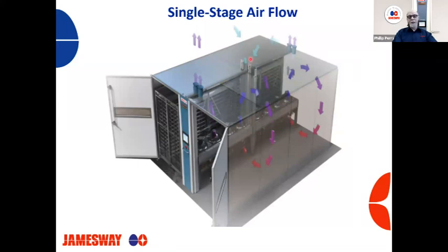But anyway, again, this machine wants the air available kind of the same way. The fans pull this air in, and then they also exhaust it out. So the cabinet sort of has its own little pressure system going on. We do not want to force air down it. It'll mess up our airflow and our temperature throughout the cabinet.